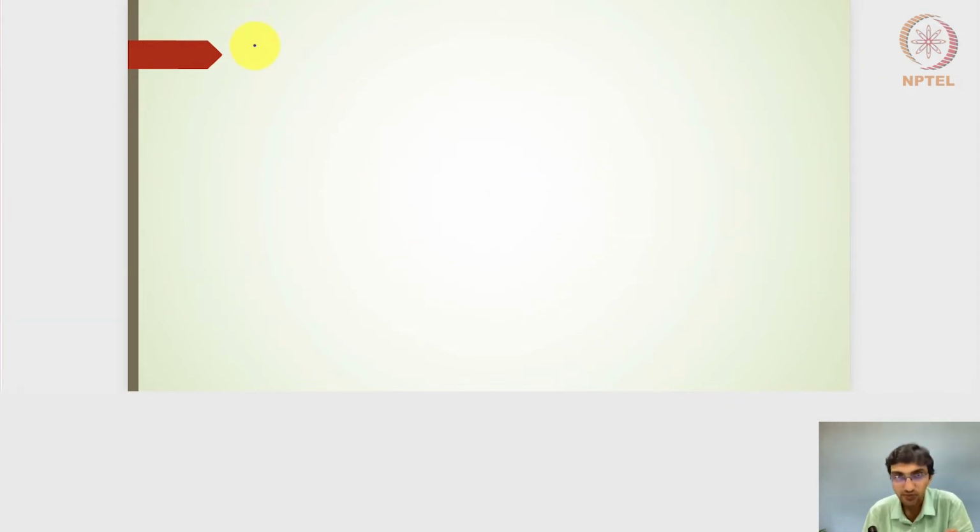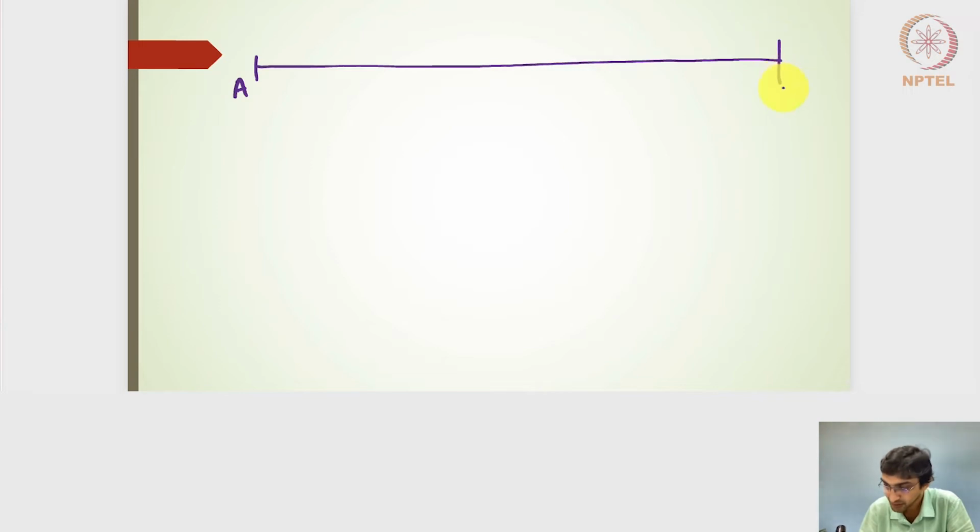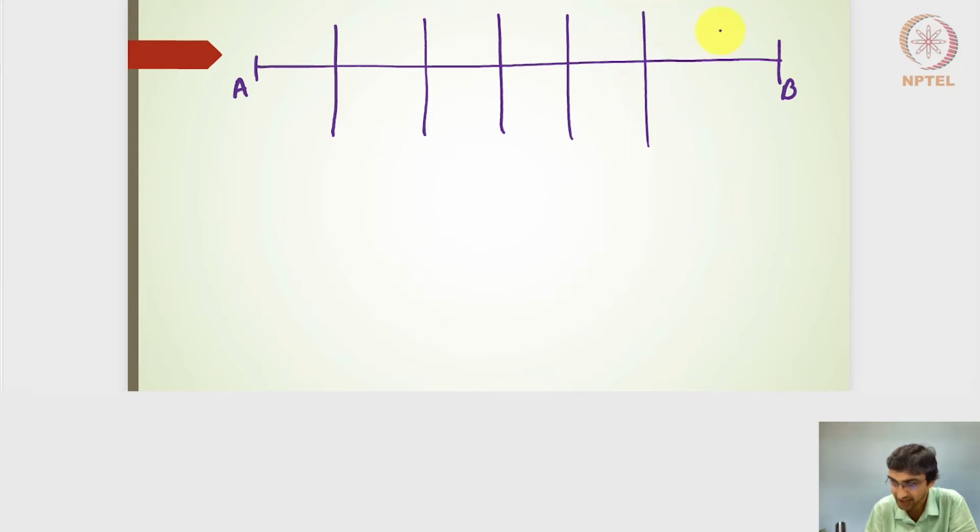So let's once again look at this long wire. Let's say I have a long wire, this is A, and this is B. At A I will have a driver circuit, and at B I will have a receiver circuit. Let's say I'm going to add a repeater so that its attenuation gets improved, so that when it reaches point B, it will have the same signal strength as at point A. I'm going to add N minus 1 such repeaters, so that I actually segment the wire into N segments.